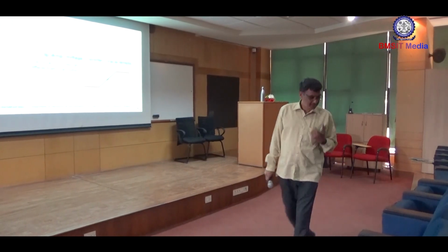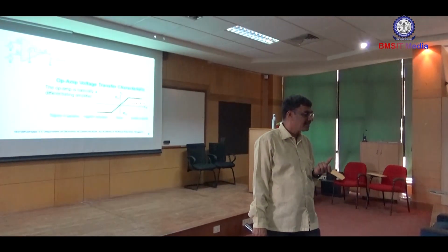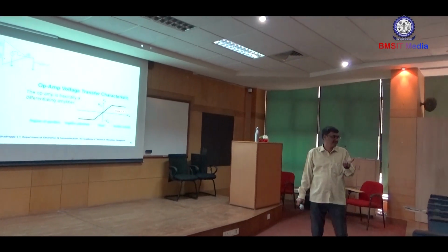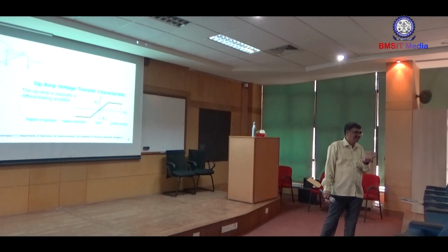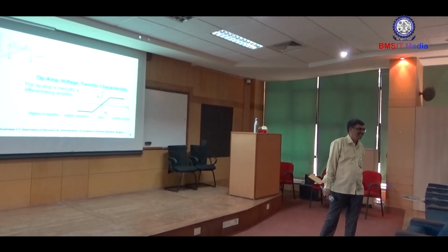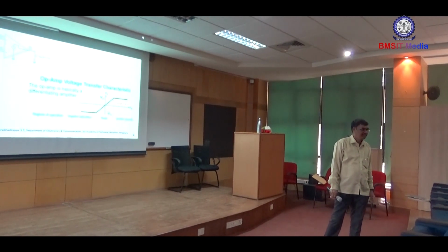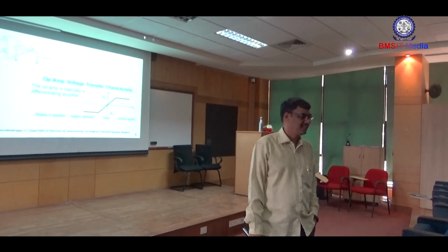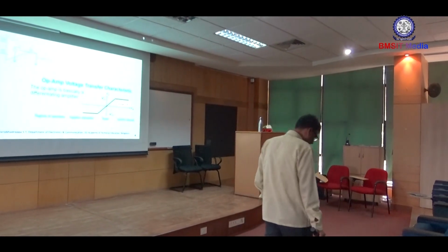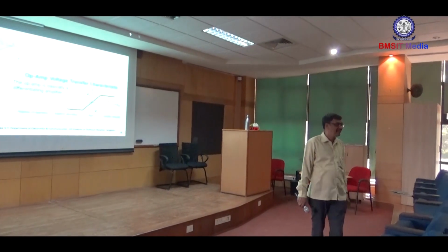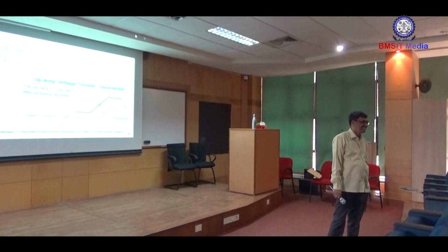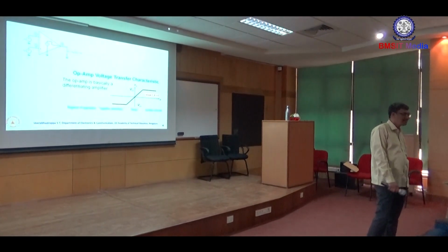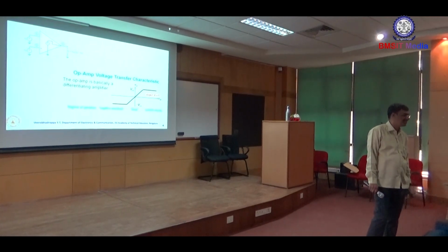You have done 2 experiments, no? Those are the transistor amplifiers. If you remove the capacitance across RE, see what happens to the amplifier. I hope you studied a common source amplifier with feedback, with source resistance and without source resistance. What is the effect? Stability increases, or sensitivity decreases, which means definitely noise reduces.